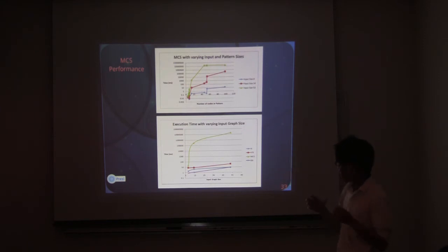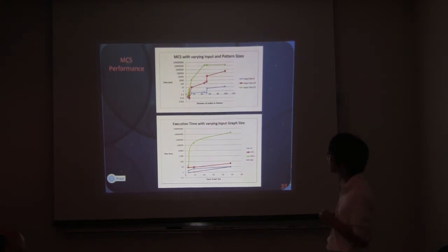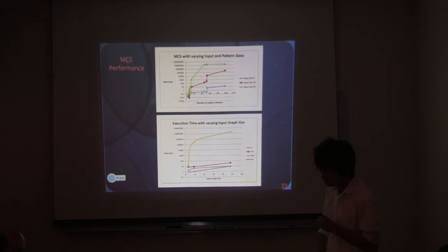The reason is that as the circuit grows, there are more possible nodes in the compatibility graph, so the graph becomes very dense, and the algorithm has to go through many possible matches to come up with a match. So with larger circuits, MCS suffers greatly in that aspect.